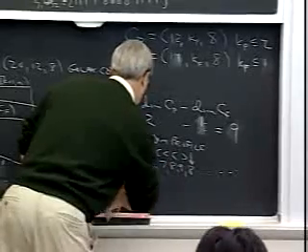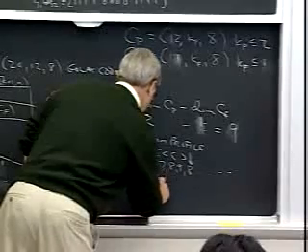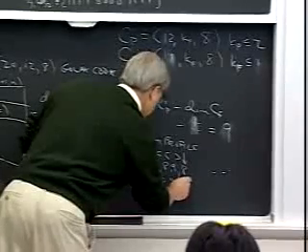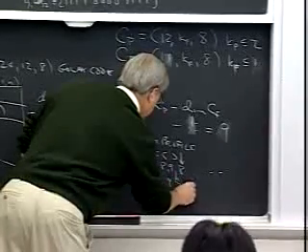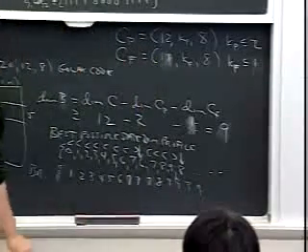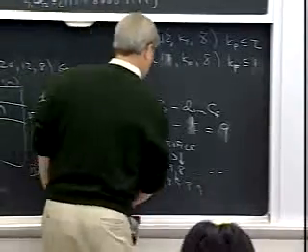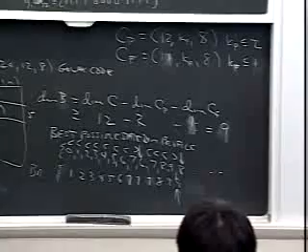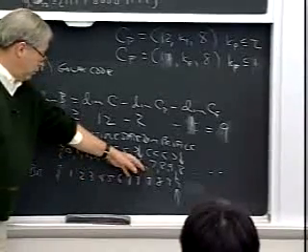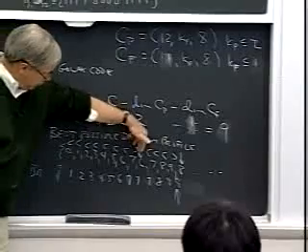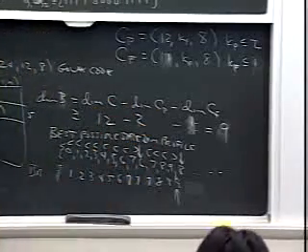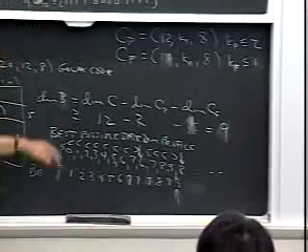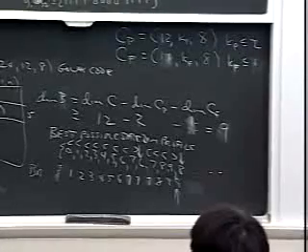That can't be right. It comes down, 7 goes up, it's still 7. Then it goes up to 8, 9, and 9. Something like that. That one's probably wrong, and symmetrically, this 9 is the one we just calculated. Similarly, if you come down to the neighbor of this 6, it's got a merge on one side, a diverge on the other side, and it's 7. Okay, so we conclude that the Golay code has branch dimension not less than 9.